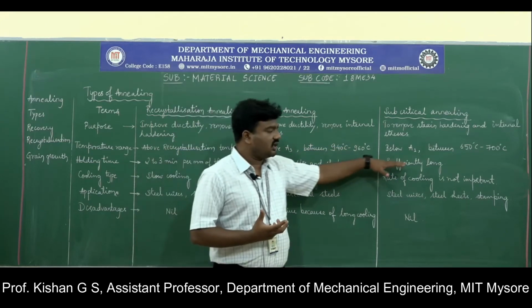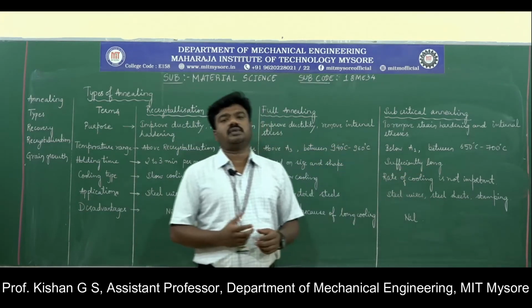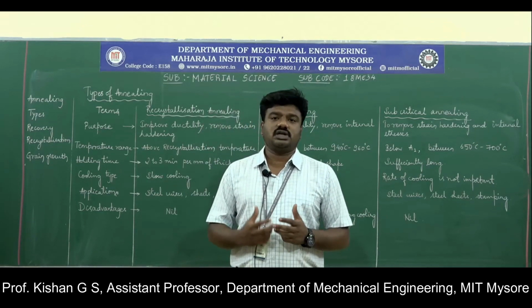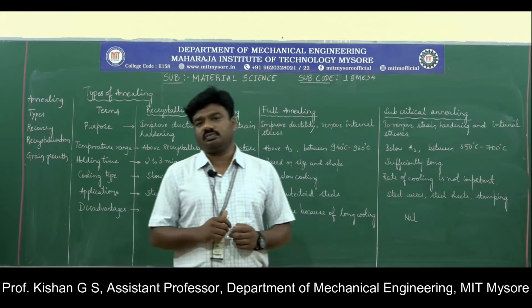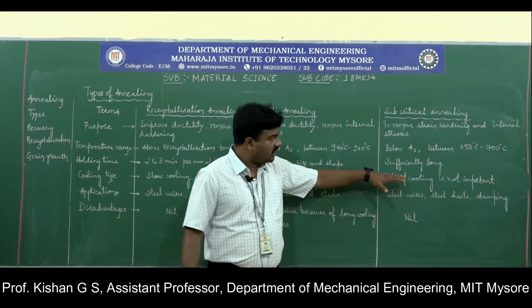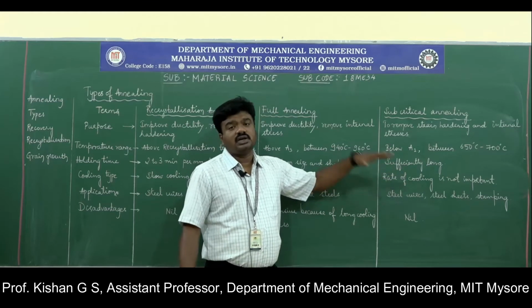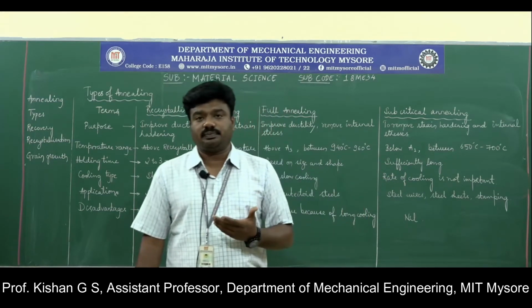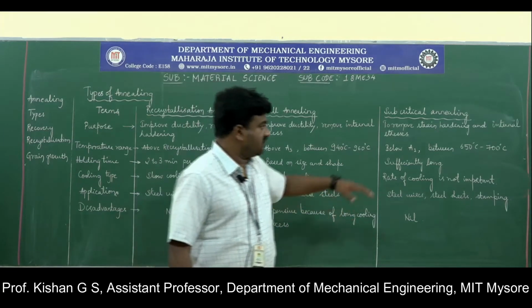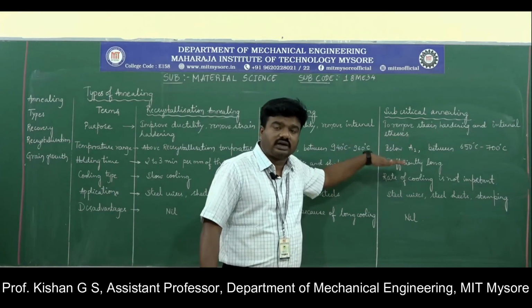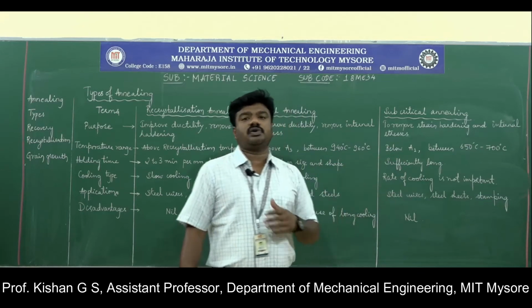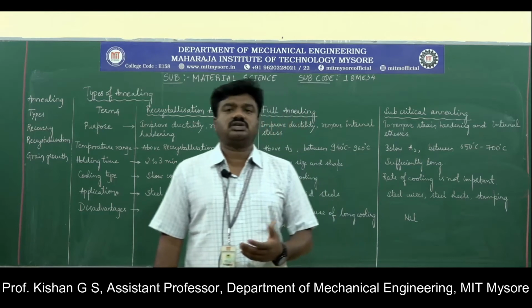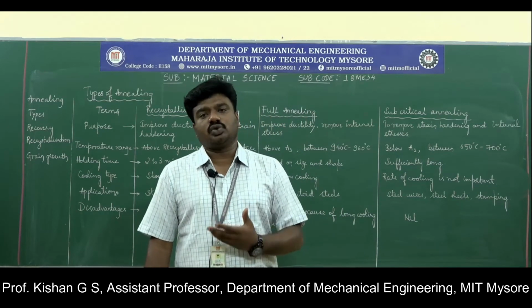And then comes the holding temperature. Here the holding period is a very long period of time, and thereby it results in better formation of microstructure. And the cooling rate. Since the material is heated below the lower critical temperature and not above the upper critical temperature, the cooling rate will not be of that importance here, because the temperature considered results in gradual cooling to room temperature.